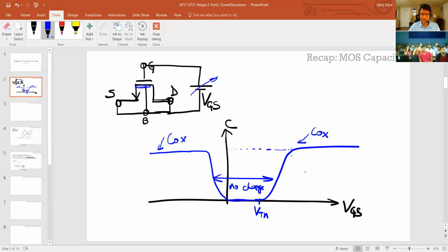So we actually use this as a capacitor. As I said, in IC design, you don't have the luxury of a lot of passive devices, like for example when you do board design. So a lot of times you have to use these devices as capacitors, and usually they are high density. They are the highest density capacitors in an IC design. You can only use this capacitor if you have a DC voltage across it.